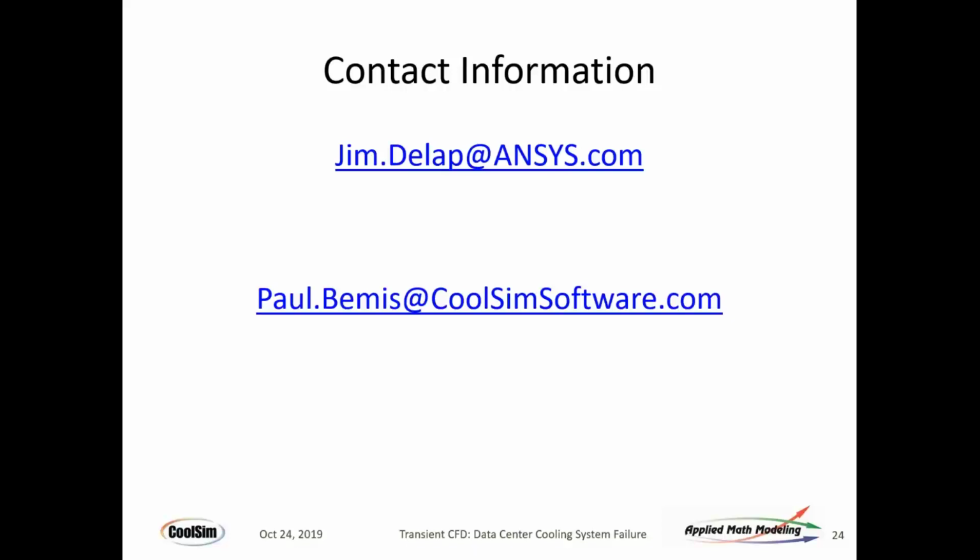Control logic has a lot of importance here because it depends what resources are at the site. It is not unusual to find they have a reservoir of water, for example, that they can use. I have one customer who has an underground aquifer that they can draw on. So that's a kind of an infinite heat sink to draw upon that they use most of the time. They don't compress very much at all. They only compress once the reservoir has gotten to a temperature they can no longer use. Then they'll start to use a compressor. So failure mode for them is pretty easy. It depends on the exact configuration that you're looking at.